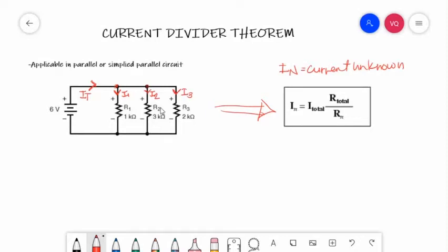Now, the characteristic of a parallel circuit is that the voltage across this resistance, this terminal R1, is the same as our source voltage. Diba? Kung natayo nga ti E, total voltage is equal to the voltage here, E1, the voltage drop at R1, is equal to E2. Same here, if you put a voltmeter across this resistance, it will read 6 volts. So, E2 is equal to E3. And the current flowing here, I1, from our Ohm's law, I1 is equal to E1 all over R1.